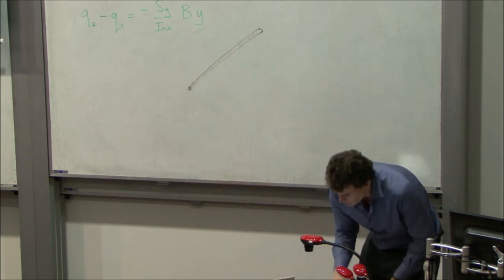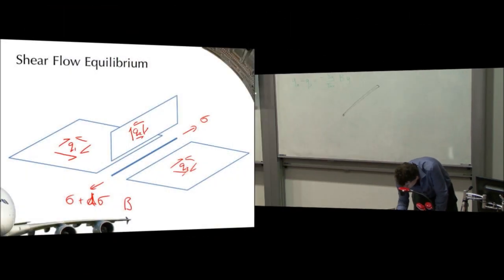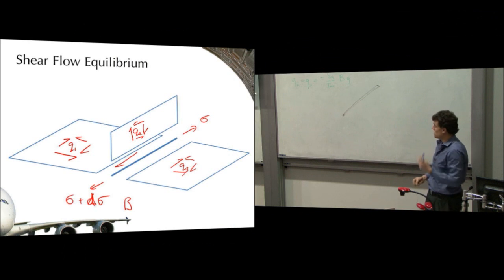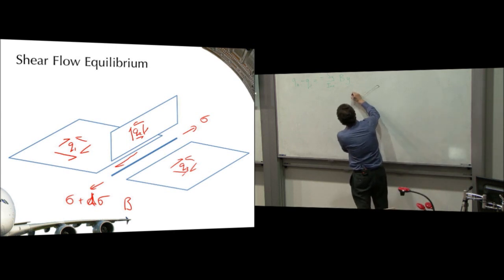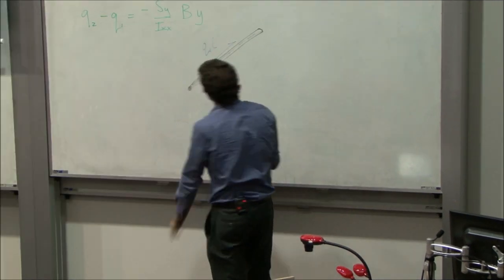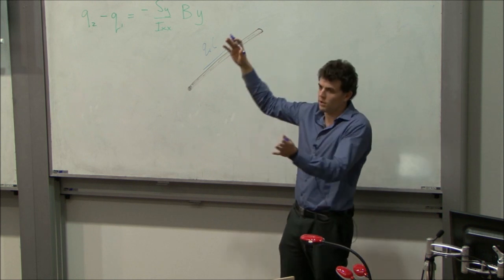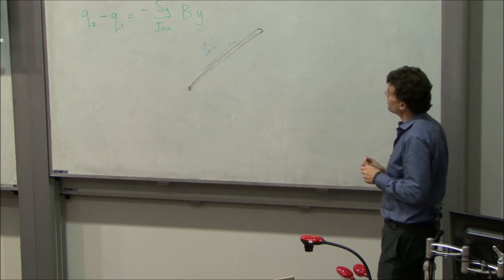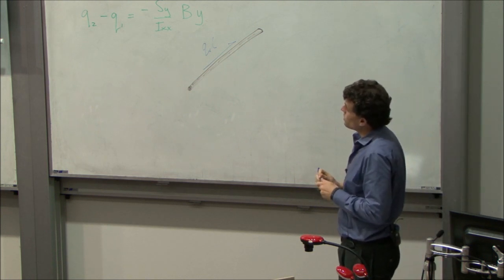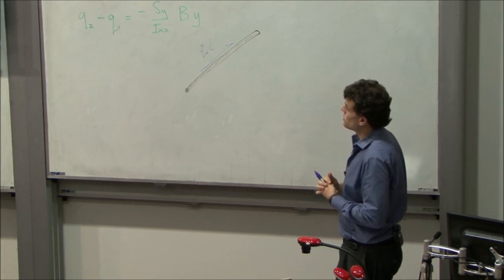The shear flow in this panel, on the edge of the panel, is acting towards the front of the board. So the reaction force that it applies to the boom is the other way. So we have a force on the boom which is equal to the shear flow times the length over which it's acting. And I haven't marked the length on the diagram, but the length of the section that we're looking at there. Now, for Q2, which way is Q2 going?